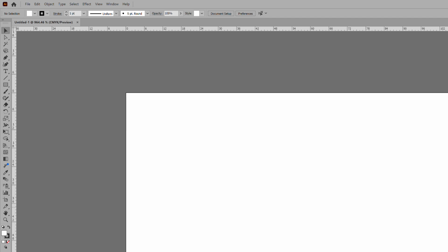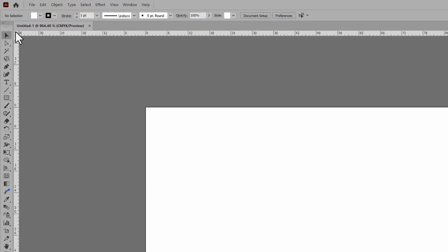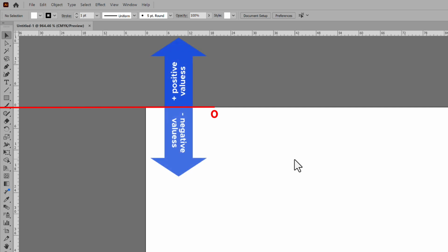The first thing to know about Illustrator is the coordinate system. Like most applications, if you double-click the top left corner of the ruler, the 0 point is reset to the top left corner of the document. However, Illustrator is based on PostScript, which uses a coordinate system where 0 is at the bottom, not the top. So keep in mind, in script code, a positive value goes higher off the page. Negative values go down onto the page.